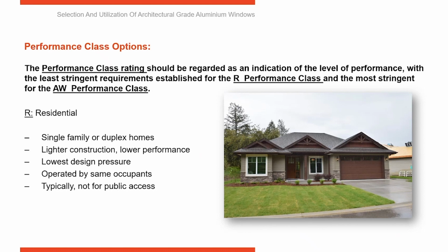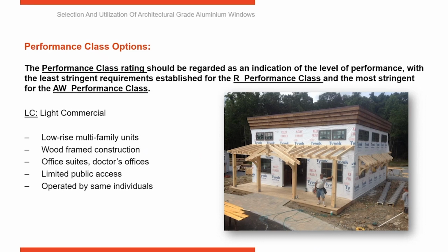Moving up from that is LC or light commercial. So light commercial, start to think about, say, a doctor's office or office suites. It's low to mid-rise application, still wood construction in most cases, nailing fins being used to install the windows. Typically the same occupants, it's going to be whoever's in that office area is going to be operating the windows. So it's limited public access.